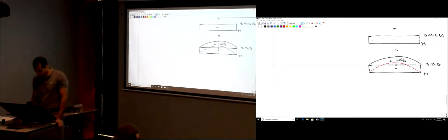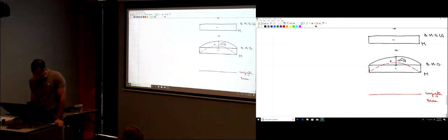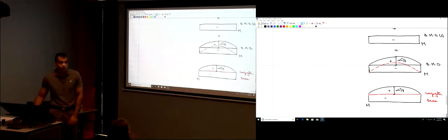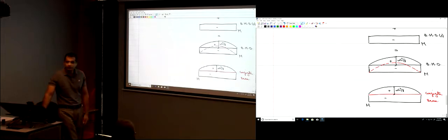So now, the next step is putting this onto the conjugate beam, assuming that this bending moment diagram is a load on the conjugate beam. So this is the conjugate beam. This parabola here, WL squared divided by 8, is positive, and this is M, which we don't know how much. This is negative, we just put it on the conjugate beam. The conjugate beam would be a free beam like this. Free, because the real beam is fixed. So the conjugate beam is going to be a free-ended beam.